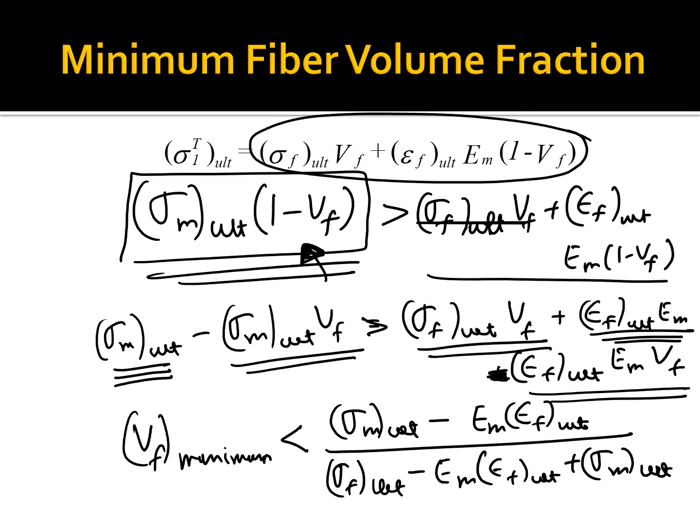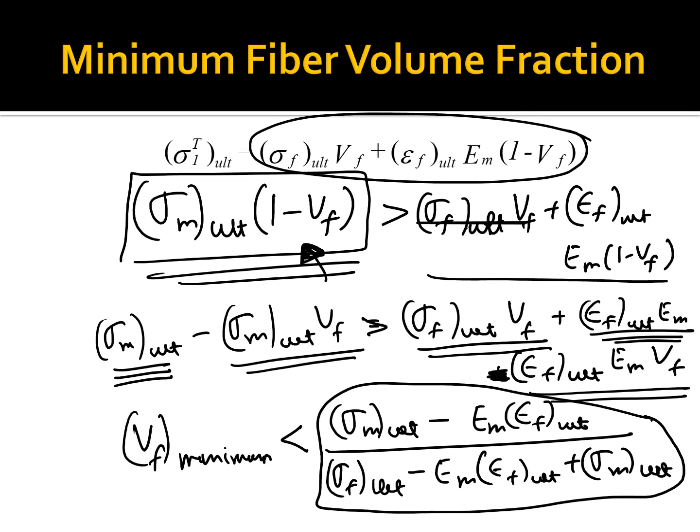So if the volume fraction is less than this particular quantity, then you will find that after the fibers are broken, the matrix can still take more load.